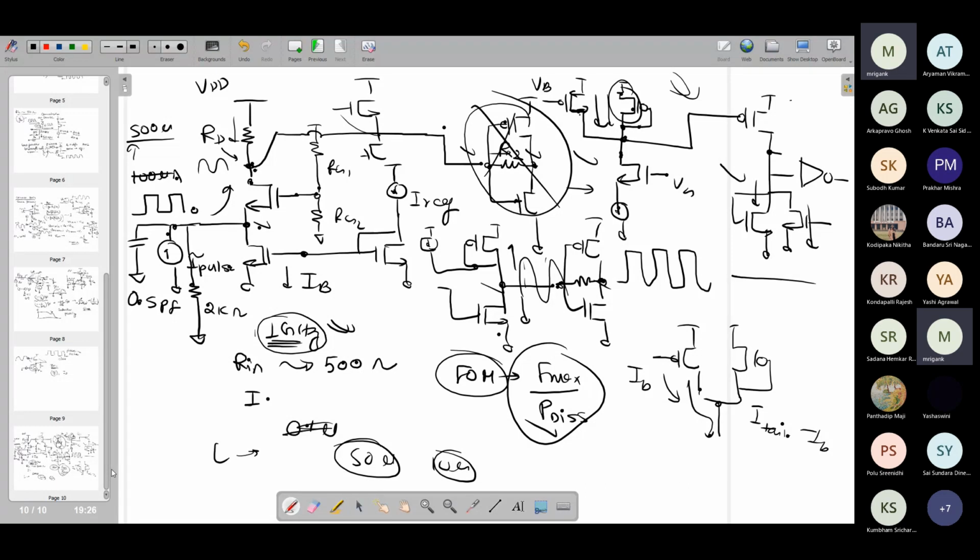So you have all the tools for doing this. You have all the common single stage amplifiers. You have common drain. The moment you want level shifting for interfacing 2 different stages, you can use common drain. You have common gate as the input. You can use common source for getting more amplification wherever required. All those things you can do.